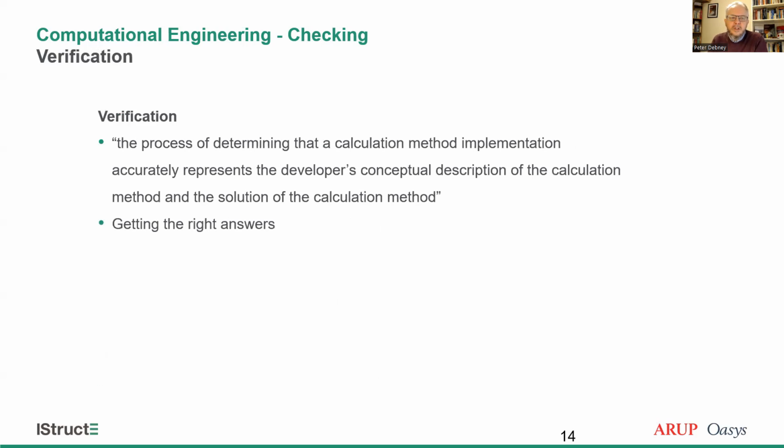So, there's also validation and verification, which is essentially making sure you get the right answers. Again, you can verify the software. Can the program give the right answers? Now, the software manufacturers will be doing this as well. This will be a main area of their work, or should be if they're professionals. But it's also good practice for you to run a few test models. Make sure that you are getting the answers you expect.